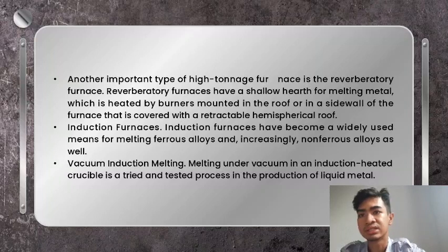A modern mid-sized steelmaking EAF can produce a quantity of approximately 80 metric tons of liquid steel in a time span of roughly 1 hour. The time quoted here is the elapsed time between charging the furnace with cold scrap and tapping the furnace. For comparison purposes, a modern basic oxygen furnace can produce 150 to 300 tons of liquid steel per batch in roughly 30 to 40 minutes.